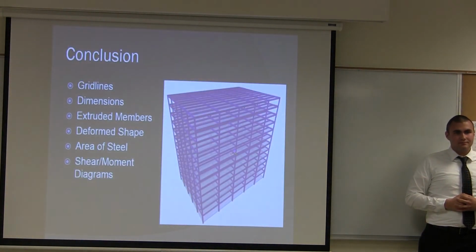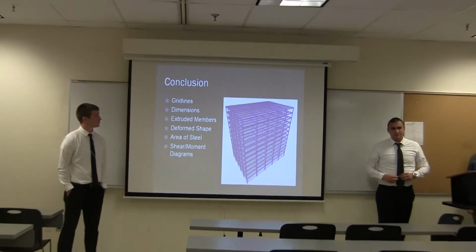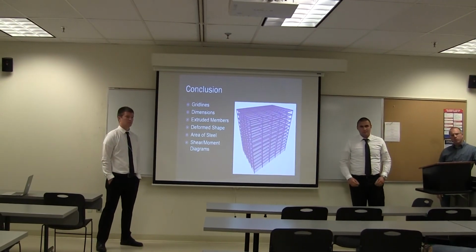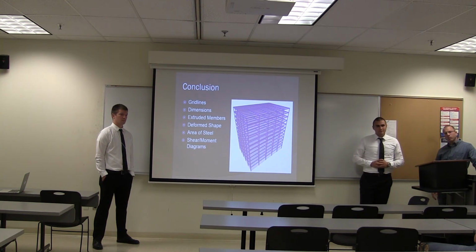Any questions? I don't have a question, but I have a statement that might help you figure out your issue. You are designing your beams as columns, and that's why you're getting your stress to show in pink on there. So if you go back and define your sections, you need to make sure that you change it to a beam design and not a column design.